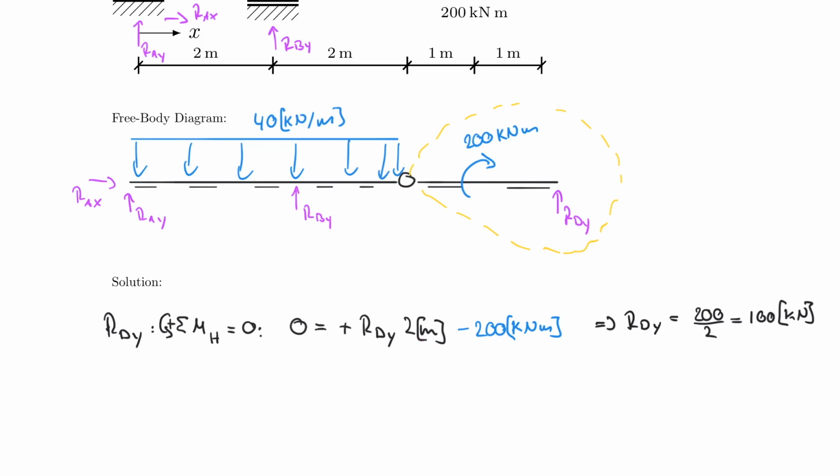And now you have the problem that you have one vertical support reaction, but still 2 unknowns in the vertical direction. So it's not as convenient as we had before, where you could just take the sum of the forces in the y direction. But what you can do to find RBY is what?